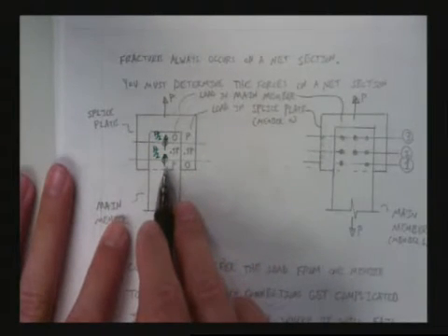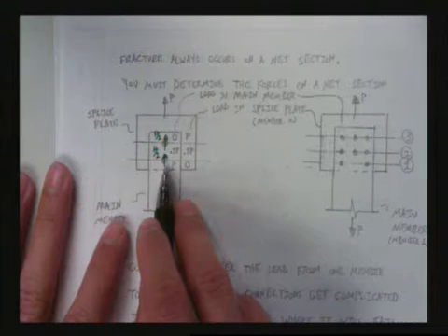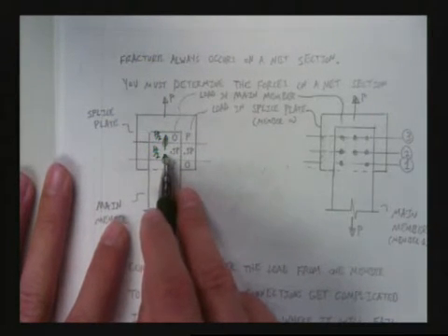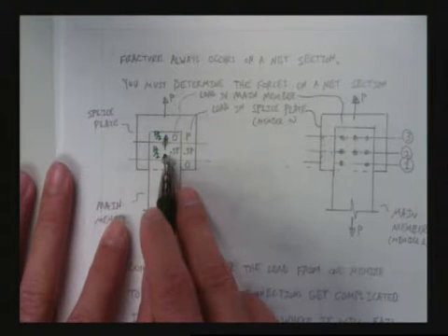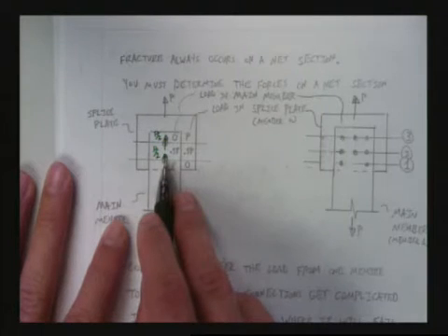So that's ideally what happens, and that's why we ideally do it that way. Now it is possible if bolts are misdesigned, or if connections are extremely long and you need lots of deflection to occur to engage all the bolts, then you will get individual bolt failures. And you will not get the full capacity that you think.